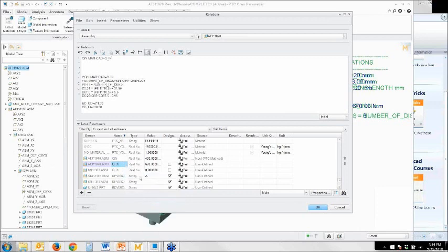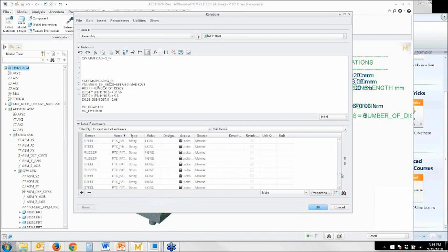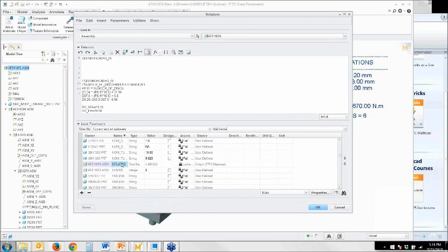In this example, there's a QIN parameter that existed in Mathcad, and there's also the QIN that already existed within Creo, and now we're just equating them to each other. We're saying, let's take the input torque from Creo and pass that in to Mathcad, so Mathcad can start running its calculations. That's the first line in the relations editor box that you can see right there.